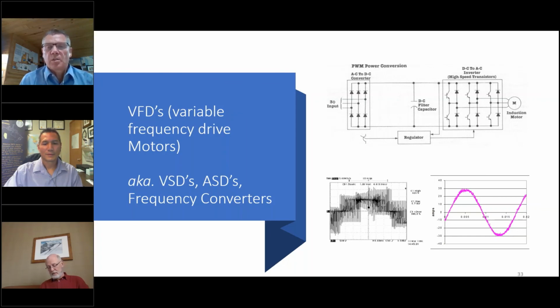And the other thing would be to set it up. If you don't have that already on site, if you had it uncoupled, run it, and then make a notation of where that end of shaft is, and align it like that afterwards.